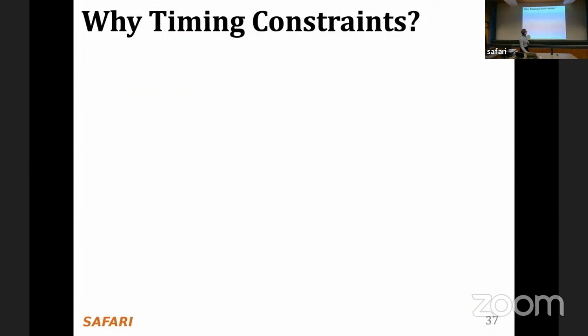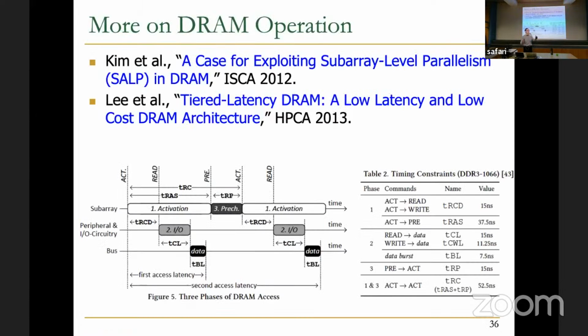Okay. So we covered a lot of interesting things, actually. But maybe there's a sweet spot somewhere, right? This is very, very synchronous. Maybe there needs to be some asynchrony. And again, self-managing DRAM is an example of trading off some of the synchrony for asynchrony. It gives DRAM an ability to reject commands, saying, oh, I need more time to do this stuff. So don't bother me for a while.